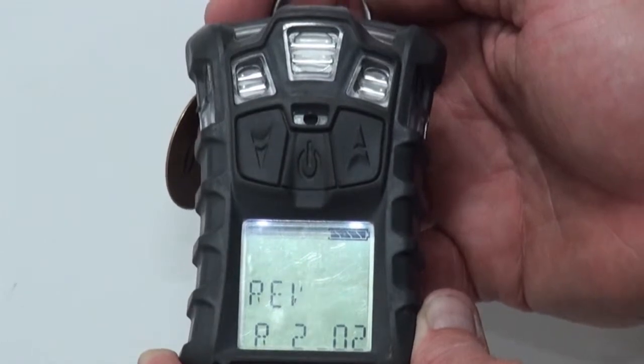So when we arrive on scene, one of our first priorities is to ensure that this has already run through whatever test you're going to utilize, whether it's your bump test or your fresh air test, that it's in sampling mode and that it's ready to go. So that when we get off of the truck, we are already sampling the atmosphere.